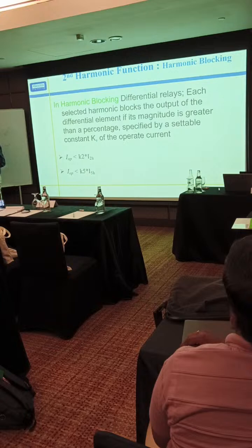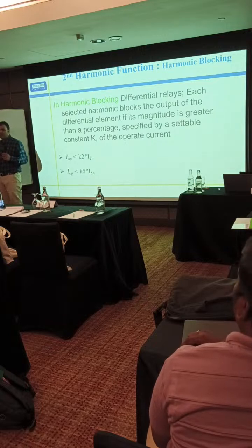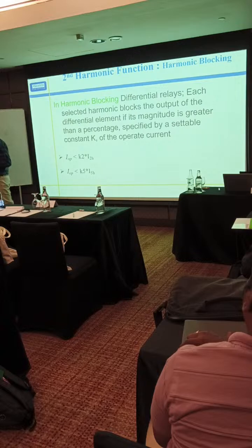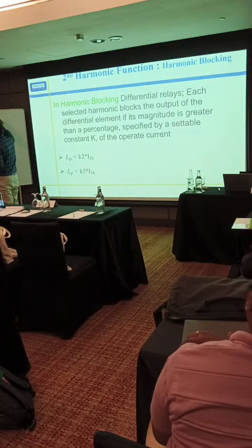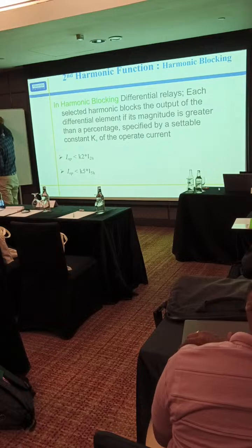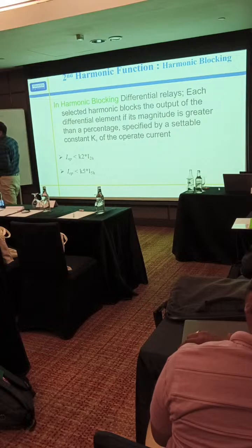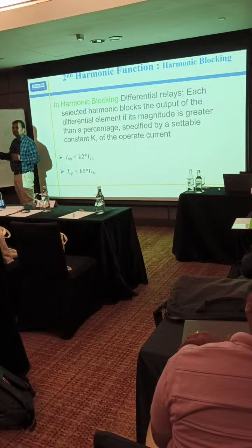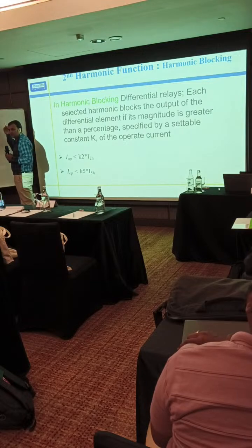So what is a second harmonic? It does not require any test plan or anything, you can manually control all these things. Suppose you have one component, this is 1 ampere at 50 hertz. If it is a 60 hertz system, then you have to select 60.